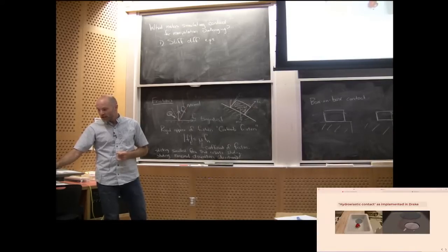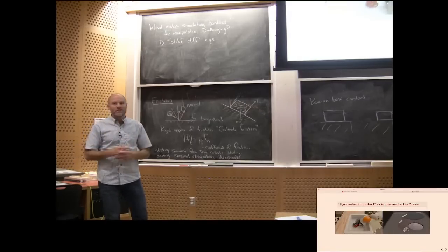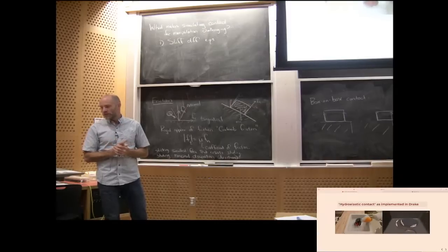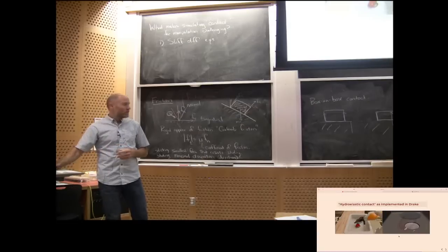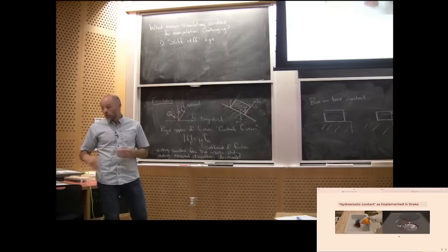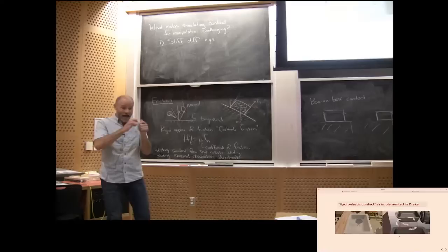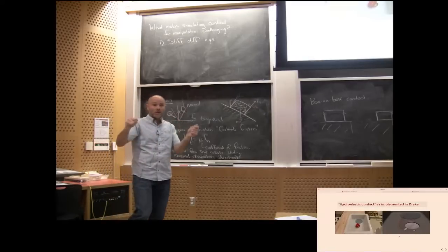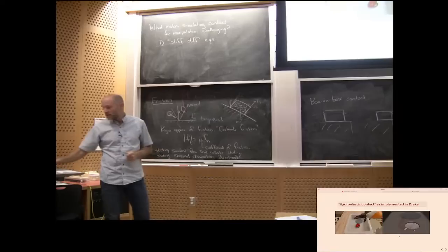So you get these great simulations if you watch the hand pick up the mug and you turn off the hand visualization and just show the hydroelastic regions. This is what turned it into a really robust simulation. This is one of the things, yeah? The other thing is a really good contact solver, so that we're not doing Euler integration. We're actually doing a much more advanced integration scheme inside Drake.